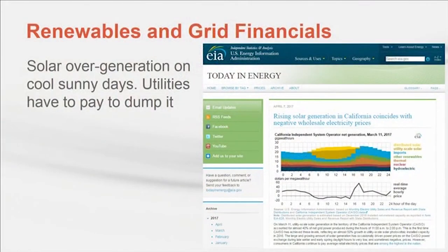So that brings us to the financial impact of renewables. When grid operators are faced with oversupply, and especially if there is a high likelihood of a peak in just a few hours, they start having to pay utilities to use it. Some power plants can't be easily turned up or down, so they have to stay online. The way that customers are encouraged to use the power is through a combination of techniques that we can loosely categorize as a demand response event.